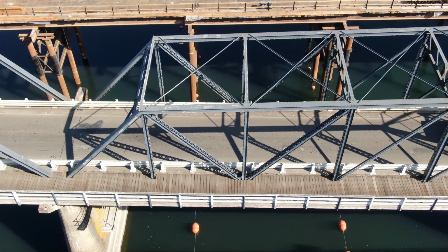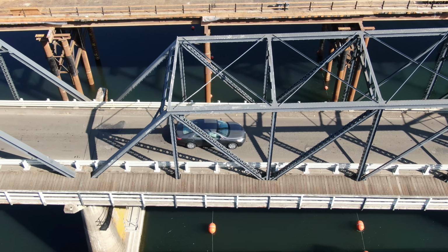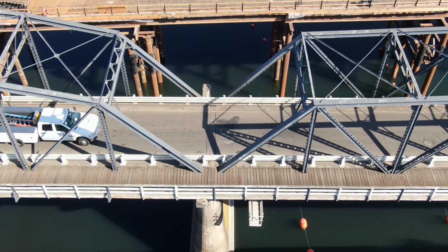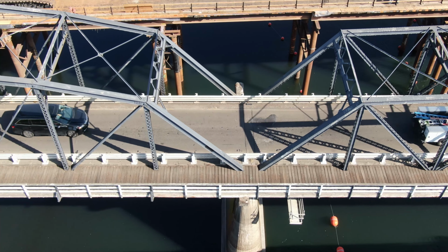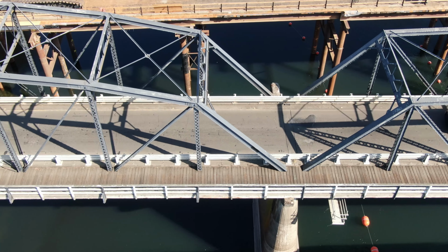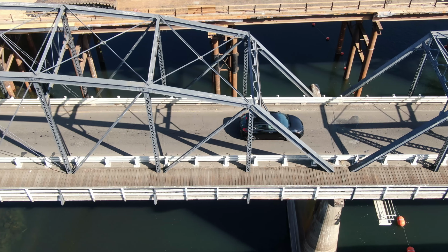Truss bridge stability is a very important topic because we want to have the truss perform as was designed, and that means the truss elements being vertical. And so you're going to see a lot of bracing on the top just to make sure that those trusses stay parallel to each other and stay vertical. So there's quite a bit of bracing in there. It's called secondary bracing, but it is very important to make sure all those parts are oriented as they were designed.